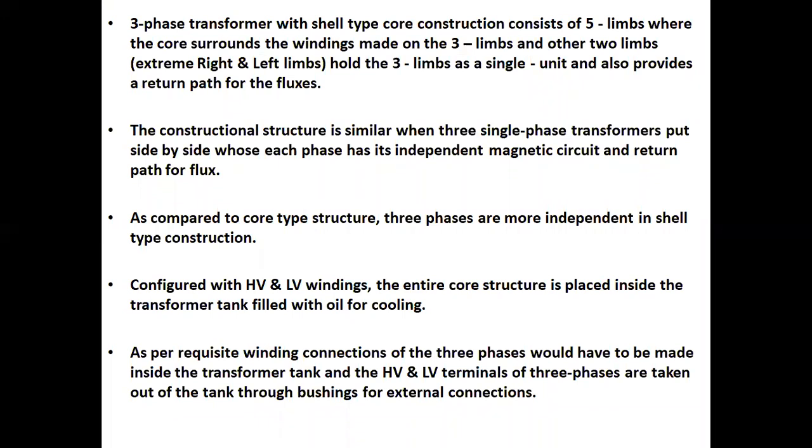The constructional structure is similar to 3 single-phase transformers put side by side, whose each phase has its independent magnetic circuit and return path for flux.